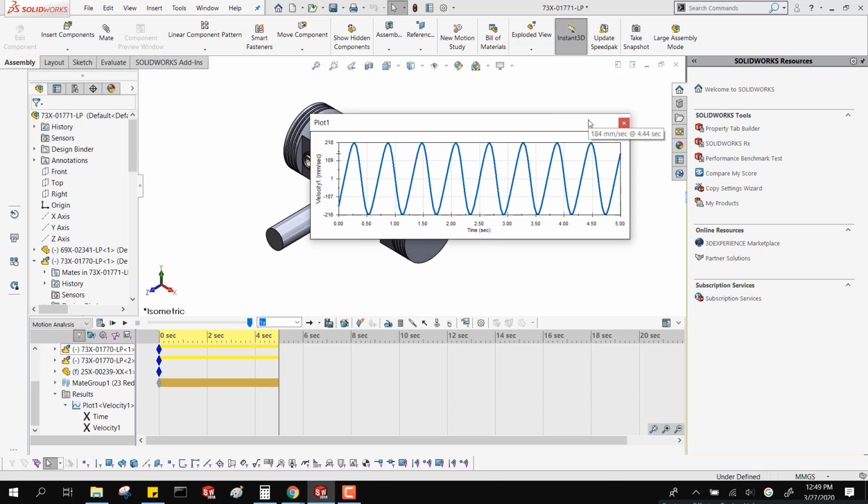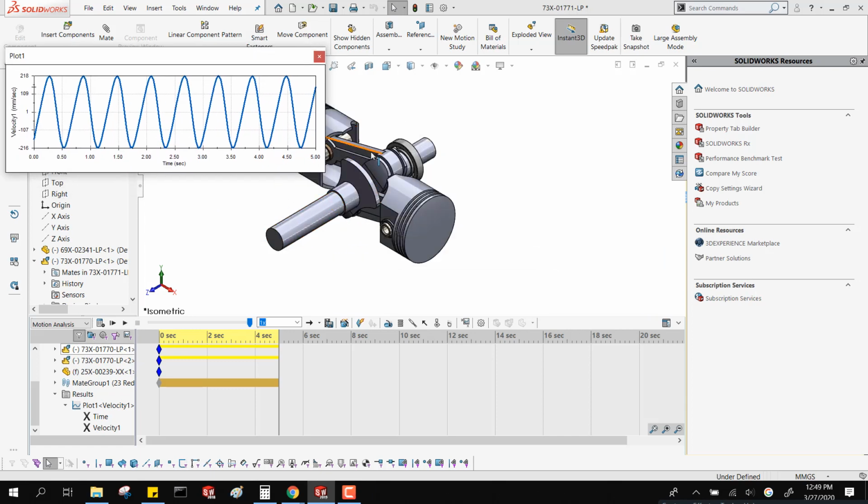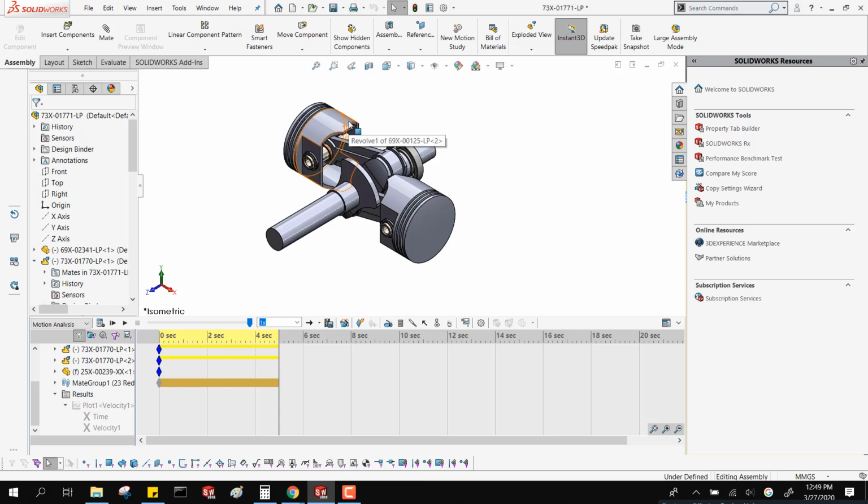So here is how fast that piston head is moving. You see that when it gets closer to the top or the bottom, the speed picks up, which you would expect, as the yoke goes up over the hurdle and then starts pushing it really fast. So you can get information like how far does this move, how fast does this go. In another example, I'm even going to show you a trace path. Hopefully that answers your question. Yep, that was fine. Okay. Thank you. Perfect.